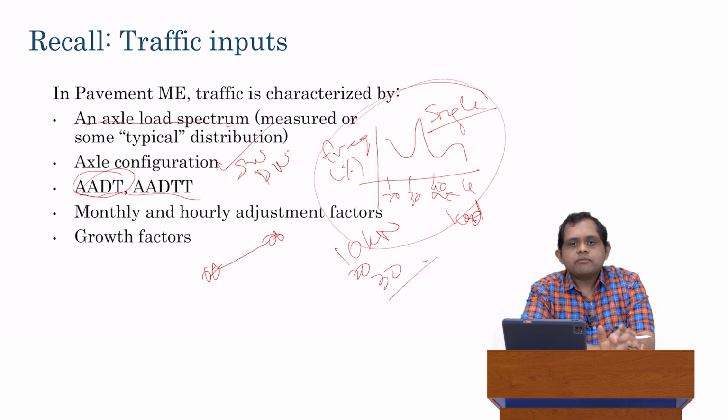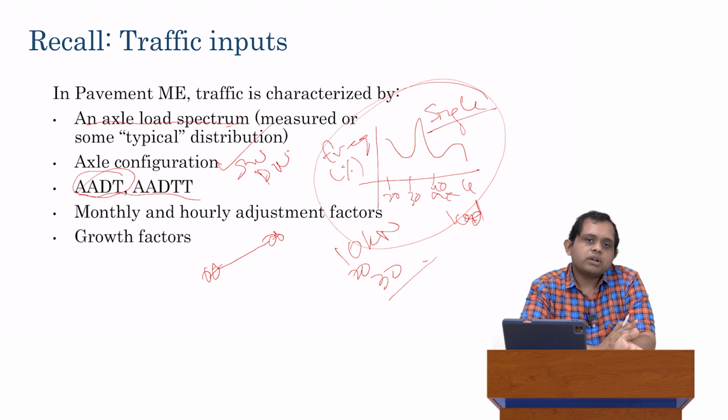And the reason we are concerned about these heavy vehicles is because the light vehicles, and light vehicles is basically cars, autos, motorbikes, non-motorized vehicles, etc., each of those is so light that the amount of fatigue damage they cause is negligible. It's either very, very small, or if you are using the concept of endurance limit, which some SN curves have, some SN curves don't, then they almost always, the stress ratio falls below the endurance limit. And therefore, there is technically an infinitely allowable number of repetitions.